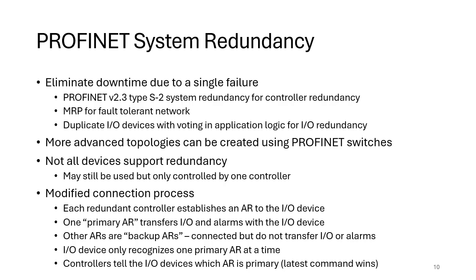But anyway, type S2 system redundancy can allow you to eliminate downtime due to a single failure. The connection process is slightly more complicated, but again, provided your devices can handle that S2 system redundancy, it's pretty much transparent to the operation of the system.